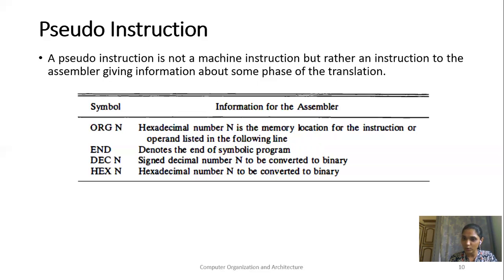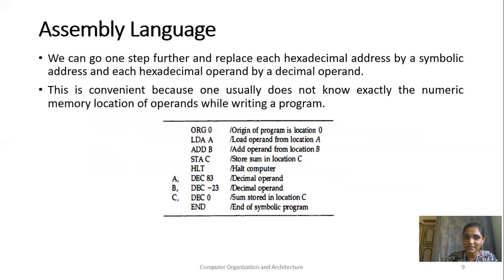So we have a total of 25 plus 4, that is 29 instructions to do programming. And this type of programming is known as assembly language programming. This language has some rules. One more thing here: after the dash we have shown some text, which is known as a comment, which indicates the meaning of the instruction.